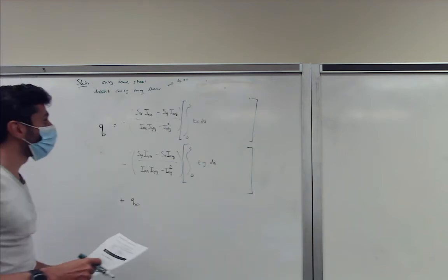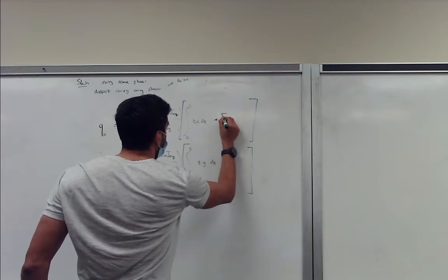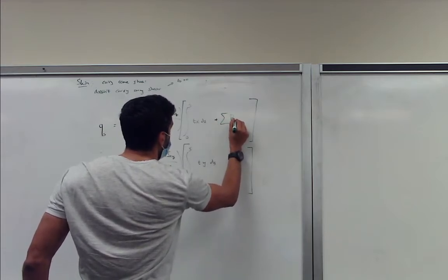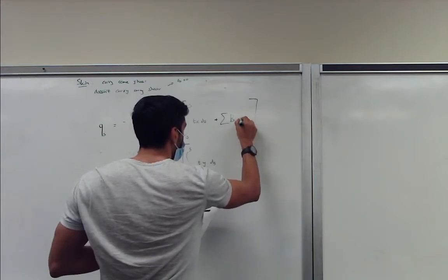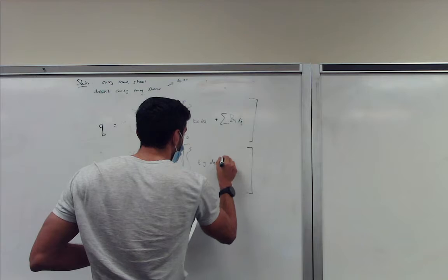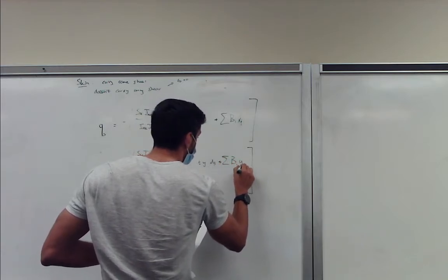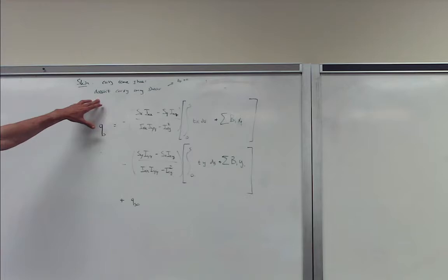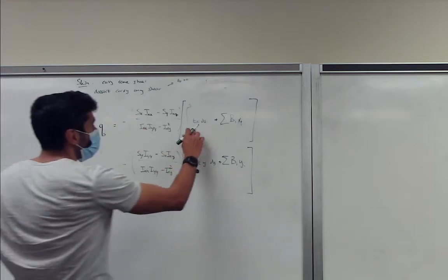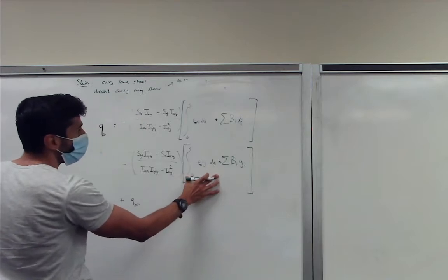And what it comes down to is that we have to add the effect of the boom areas, By, to make it complete. So this is our most generic case. And then if we assume that the skin doesn't carry any stresses, this tD basically goes to 0 and the integral drops out.